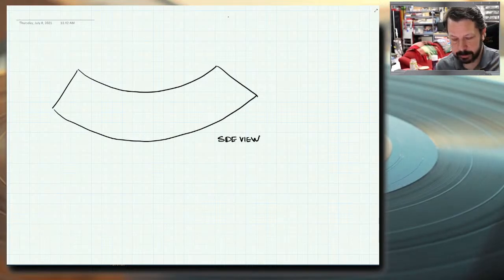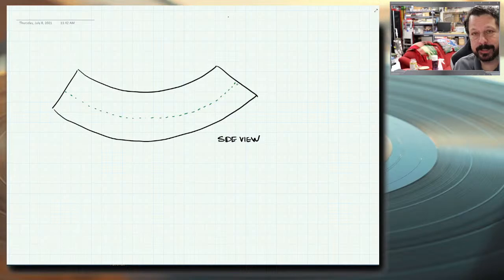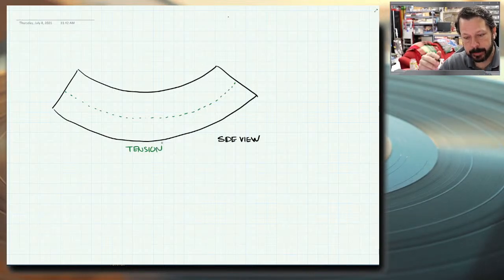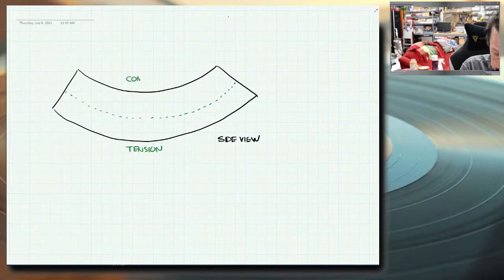If we started out horizontal, flat, not bent, we put some kind of loads on it and it ended up bending, then somewhere in here is the original length, because we can figure that out because on the bottom here, it's had to stretch. So there's tension on the bottom. And at the top of the beam, in this loading configuration, or we wouldn't even show the loads, but the loads that create this kind of deflection, the beam has gotten shorter. It's in compression.